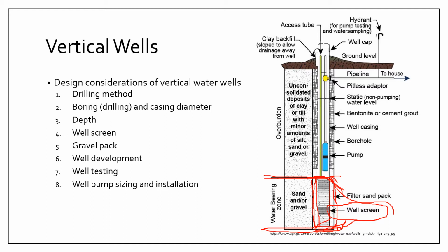And of course, all these muds and fines are detrimental to the permeability of your aquifer formation, and they have to be removed. And that is the purpose of well development.